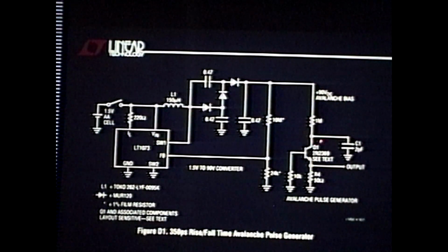I mean, right now, this thing's basically just a free-running RC oscillator. You charge through R, C dumps, and you charge some more. This thing's just a relaxation oscillator. I've got a version of it now that you can trigger, which, if I don't get into slide form, if somebody wants it, I can give it to you now.